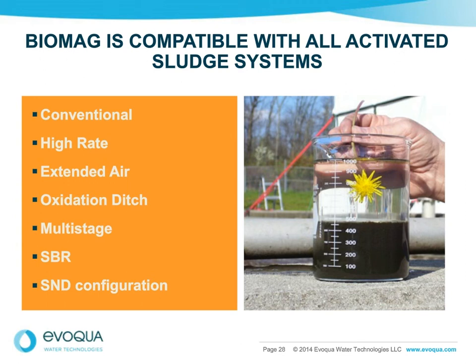We've done quite a few SBR upgrades to enhance the settling cycle, take time from settling and put it back into the react zone, and ultimately get enhanced effluent quality if that's your need from a discharge standpoint on treating your biological wastewater.